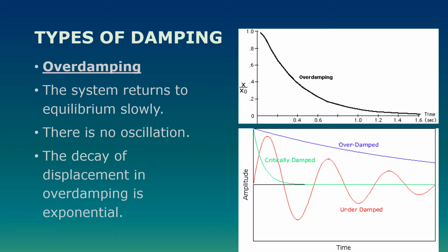And you can imagine there are uses for all of these different types of damping. There will be times where you will want to critically damp something, where you don't want it to oscillate at all. There are times where you want to overdamp it, again to stop it oscillating, but not to stop it quite so suddenly, because that might cause damage. For example, if you slam a door, it makes a huge noise. But in kitchens, quite often they have drawers that close very slowly. You give them a push, and there's damping in there to slow it down. They've been overdamped, so they don't slam and they don't cause any damage.